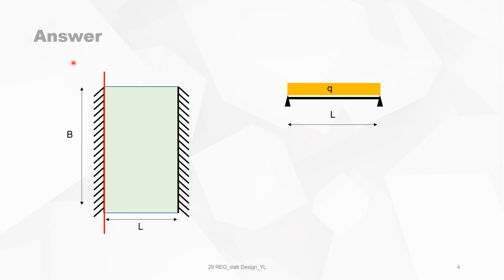Dealing with yield lines, we look up the axis of rotation, which is of course at the supports, and here too. But now we have to find a yield line, and the yield line starts at the crossing of two rotation axes.